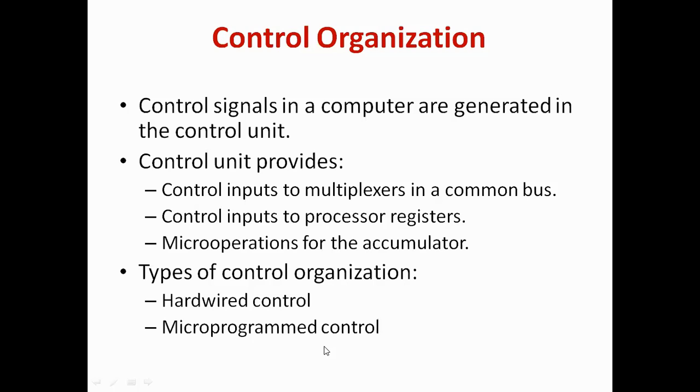So if I want to generate a particular control signal, say selecting certain multiplexer or doing some other operation, then we need to first run that program of the control memory, and then that program will produce a control signal which will do the required thing. So before doing any job, we need to run another program from the control memory. That will be a controlling program. This organization is called a microprogrammed control organization, where a program is doing these things.